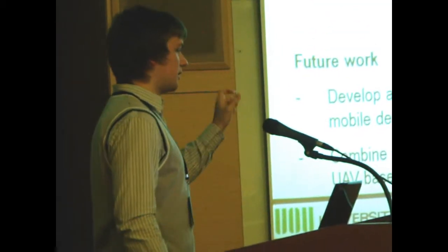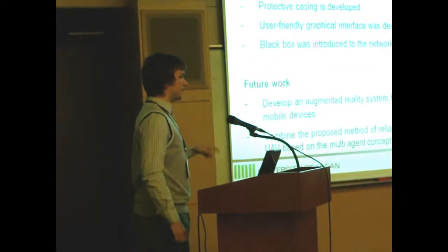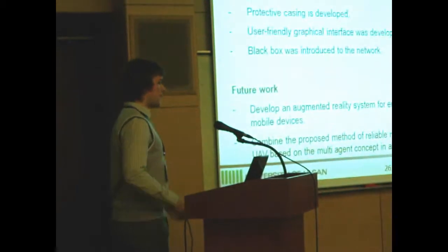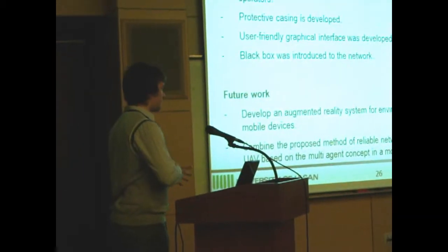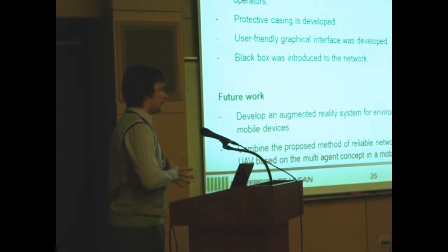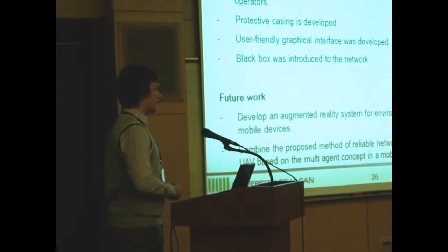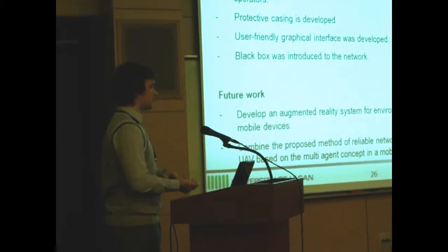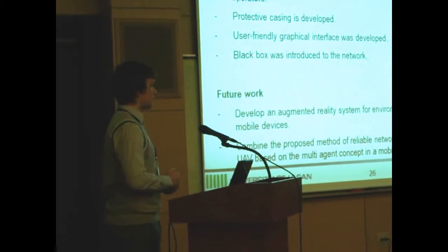They give us actually temperature like 23 degrees and humidity 80%. But the other sensors, gas and smoke sensor, give us voltage from 0 to 5 volts. We have to use an ADC to show real numbers using that voltage.